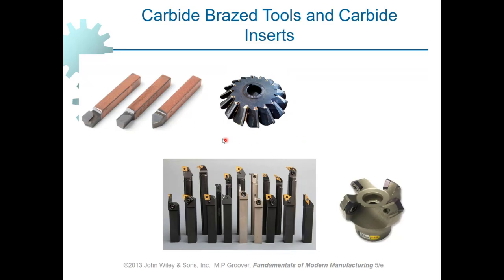And this is also a milling cutter, where we have got the cutting tips that are brazed to the shank or to the holder of the cutting edges, and this is also a type of cutting tool that is used in milling operations. Again, the type of joint is permanent, so when the cutting edges get blunt, we've got to subject the cutting tool to a regrinding operation in order to resharpen the cutting edges.